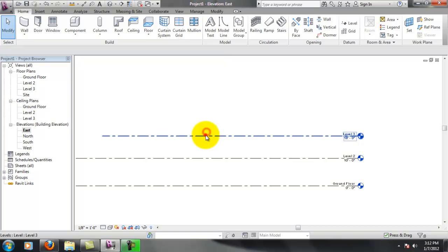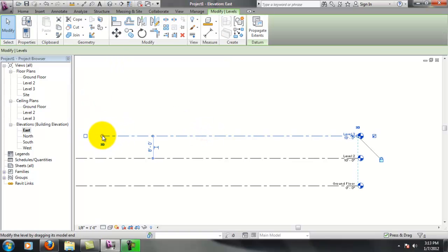Now when you click on elements, you'll see you'll get little drag bars here. These little circles represent being able to click. These check boxes have to do with datums. If we didn't want this datum here, which is this element here, to be visible, we would uncheck that, and that'll get rid of that. Obviously we want that on at least one side, but you can see Revit offers you the ability to do that on both sides if you want by checking this checkbox.